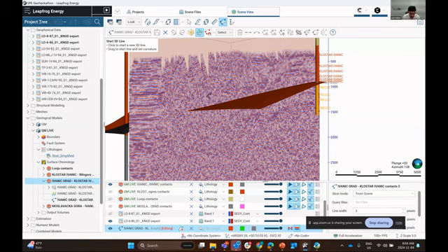And now you can see on the screen here, we have a crosshair with a little note icon to the bottom right of it. So we got a crosshair here. As we step away from 3D objects, because we have this 3D object drawing enabled, you can see that there's no object under the mouse. So for this particular polyline, we do have to have an object underneath it to draw this polyline.